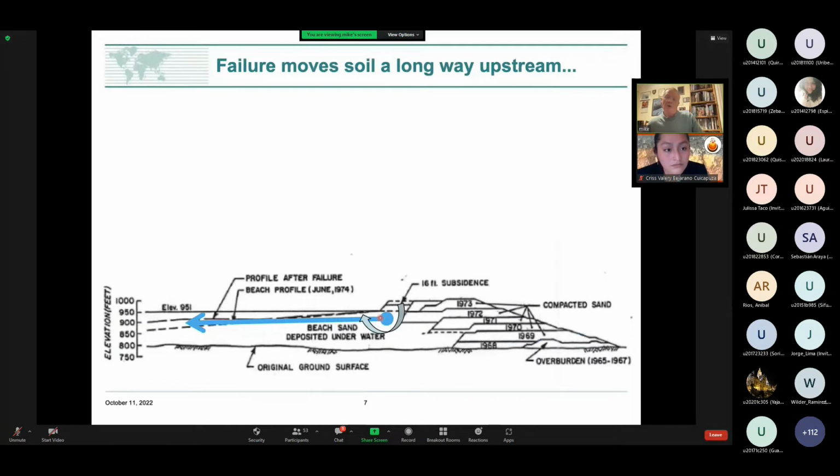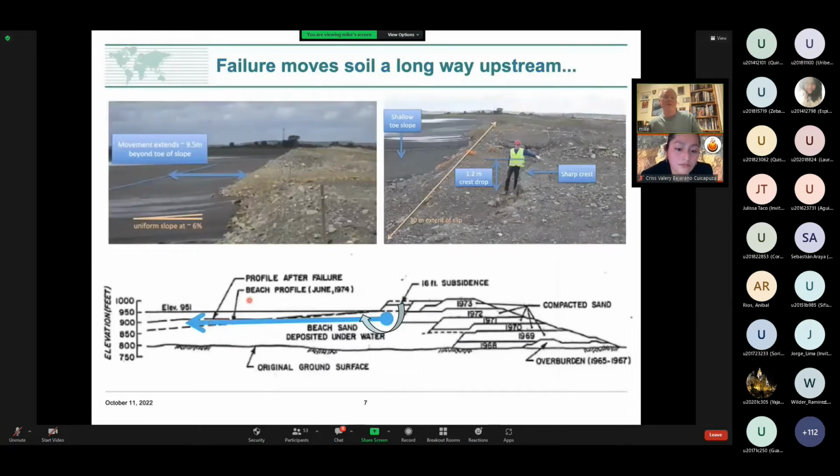If you were to do a limit equilibrium analysis around here with an Su, or a sigma-V ratio, whatever you want to do, the mechanism you'll get will be more or less a circular slip. And since this thing was only 12 meters high, you might only go about 12 meters upstream or thereabouts. It actually went more than 200 meters upstream. So the first thing when you look at this, you might say, well, are these guys reporting correctly what happened?